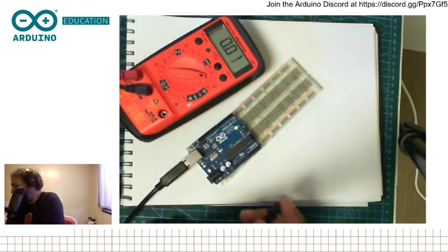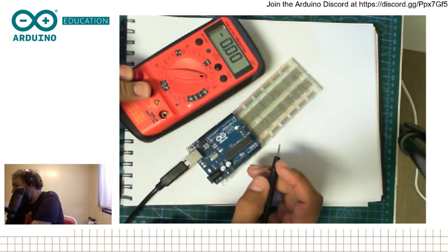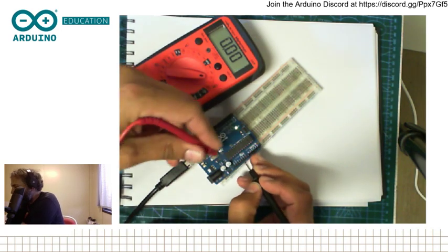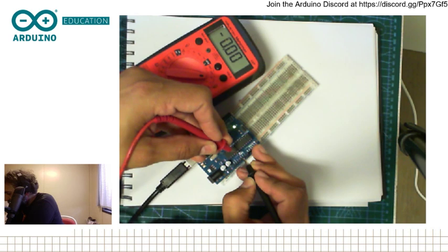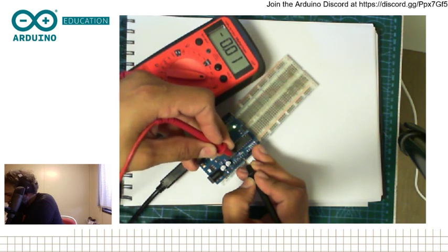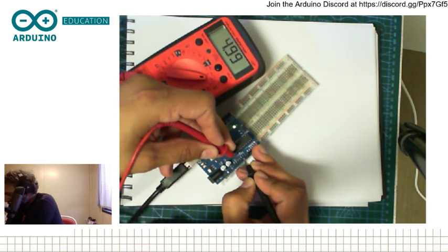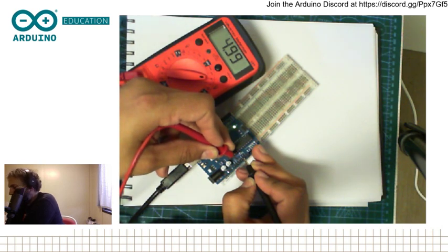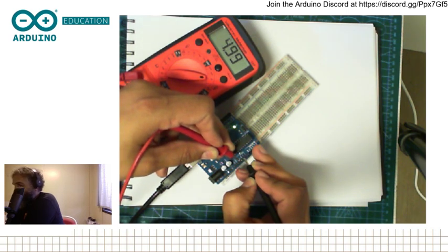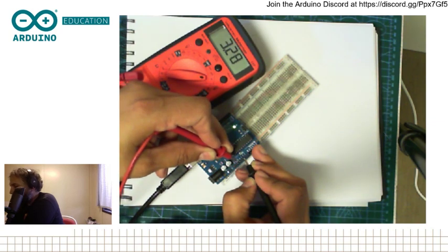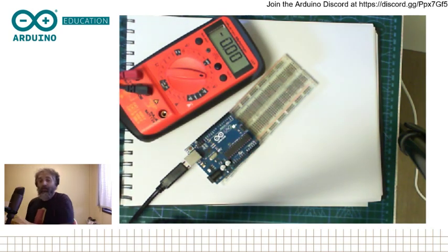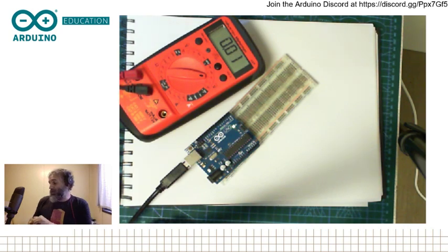And if I go down one more pin, I can connect my multimeter to the 3 volts pin. Okay, that's the 5 volts. You see, earlier I was measuring on the wrong pins, so this 4.99 is a bit more accurate. I'm going to the next one, and I get 3.28, and that's on the 3.3 volts pin on Arduino,